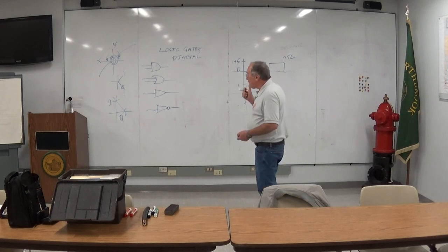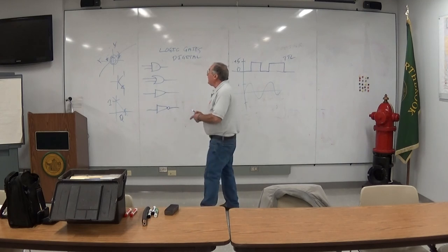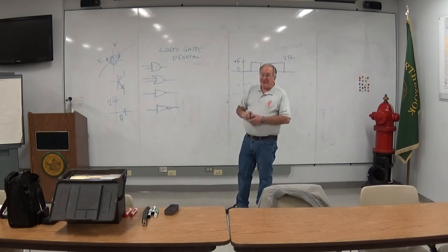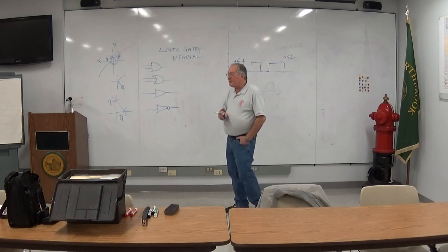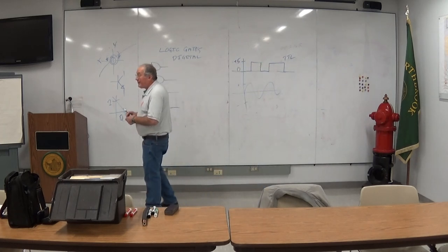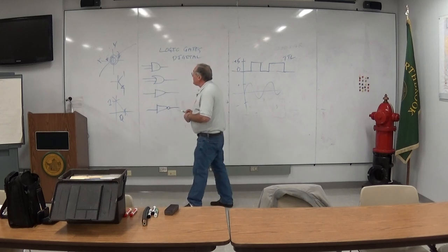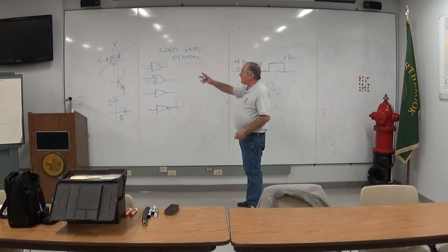They called it the destructive read-write-restore cycle, but it took 650 nanoseconds to do that. And nowadays, the random access memory chips that you normally buy do it in nanoseconds, usually less than 200 nanoseconds, maybe a lot faster than that now. So the old-fashioned magnetic core memory is long gone.